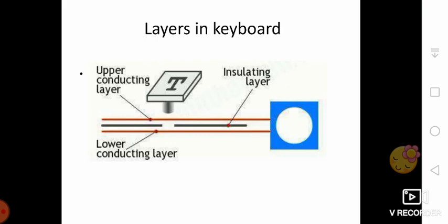Another type of keyboard has three layers: a top plastic layer with the key positions marked on the top surface and conducting traces on the other side. The middle layer is made of rubber with a hole for key positions. The bottom metallic layer has raised bumps for key positions. When a key is pressed, the trace underneath the top layer comes in contact with the bump in the last layer, thus completing an electrical circuit. The current flow is sensed by the microcontroller.